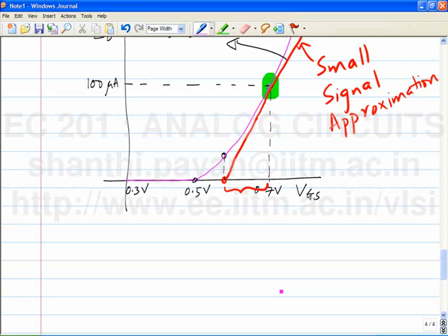However, we see that the error made is small, and to actually compute the true value of the swing required so that the current becomes 0 requires a lot more effort: solving nonlinear equations, Taylor series and all this. So the quick and dirty way, which works very well in practice, is to just assume that the transistor is linear and compute the limits of the swing.